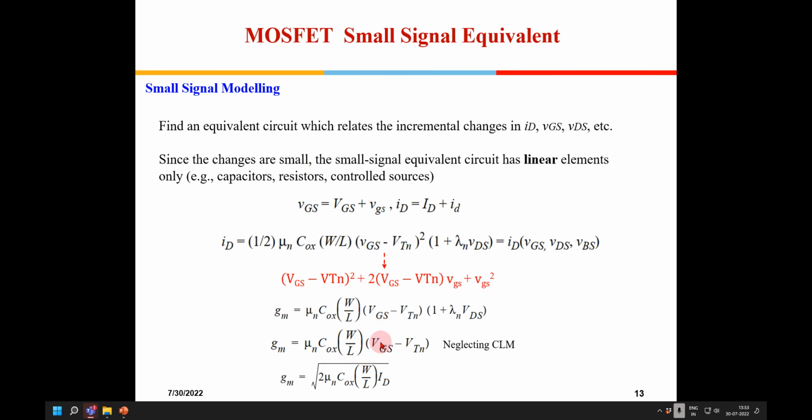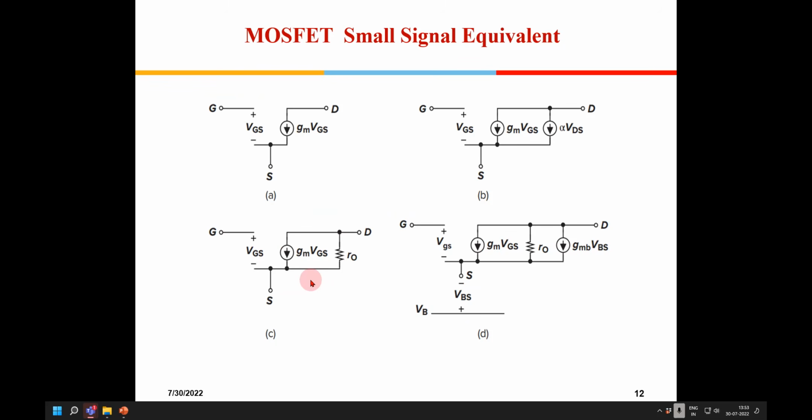Sir, I have a question on the previous slide. Normally, a specification in the MOSFET is provided predominantly for large signals: the RDS on parameter. So is it right to say that this RDS on from the suppliers is in fact the parallel combination of all three, or is it just the r0? No. r0 also depends on the length.